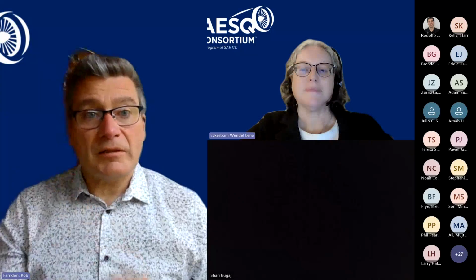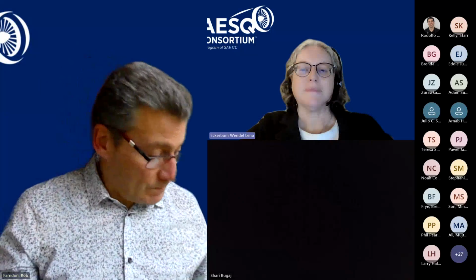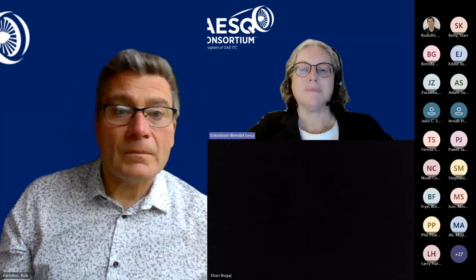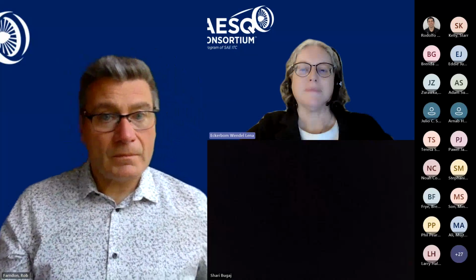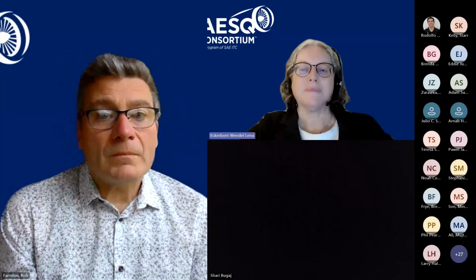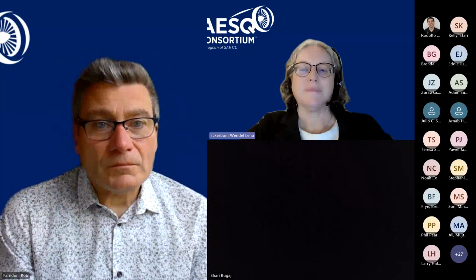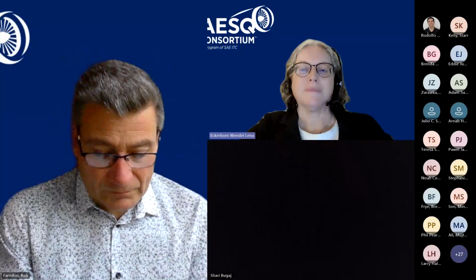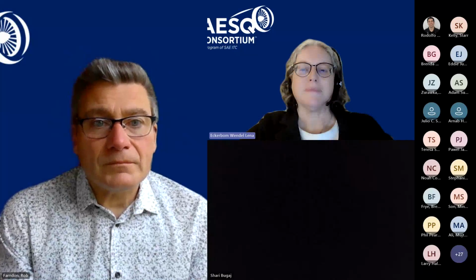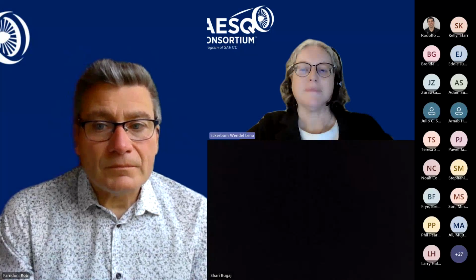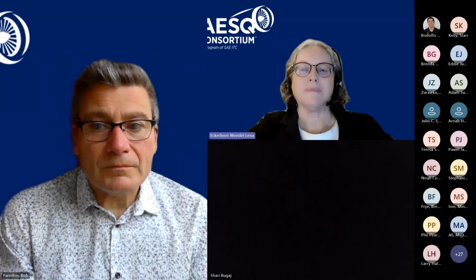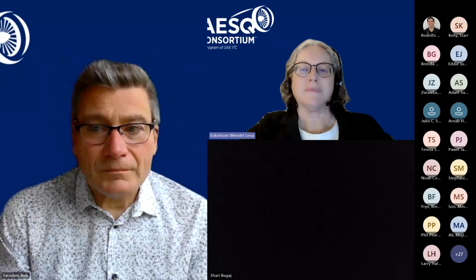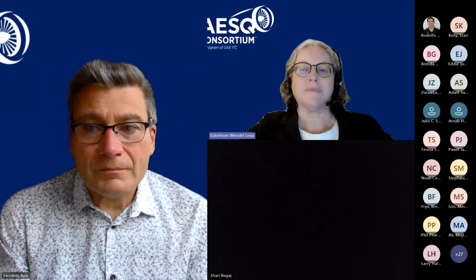Yeah. Lena, any comments? So the FMECA would be a tool in the system safety assessment, ending up with a number on what is the risk per flight hour for a certain type of engine event. So it would influence how you design your part to reduce that risk. On the DFMEA side, a typical action could be that we do 3 more analyses with different analysis tools to make sure that we have a better confidence and a better design control. So it's the same type of product failure, but we have completely different time frames, completely different mitigation to reduce those risks.